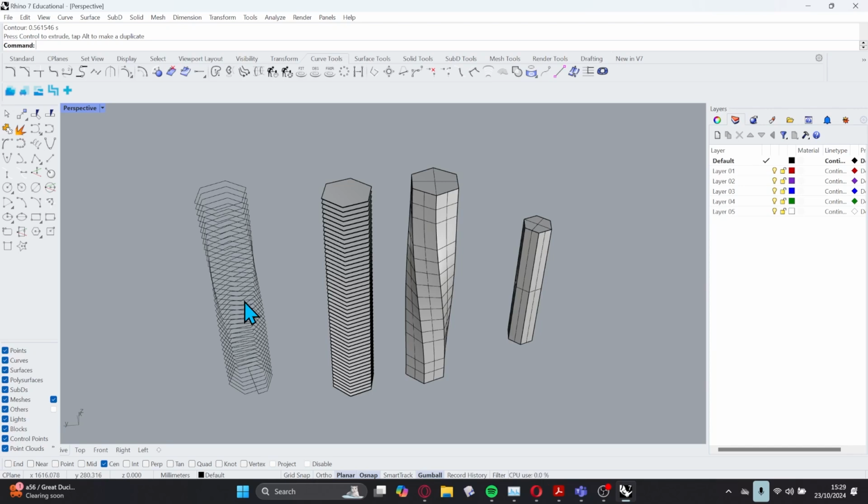So when you're trying to center an object, when you're using the center snap, you need to go to the outside of the object for it to find the center. It'll only find the center when you click the outside. Okay? I'm going around and I'm seeing some pretty cool stuff happening. Some people have done some arrays, which is great. What's that?